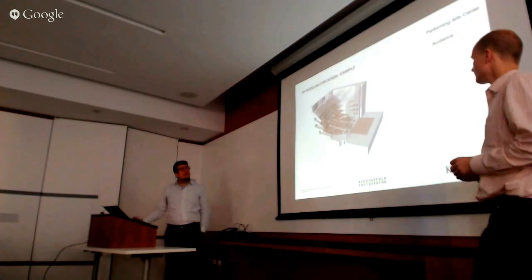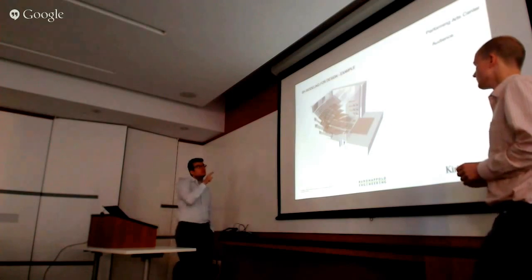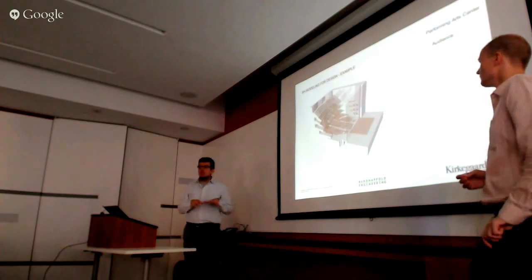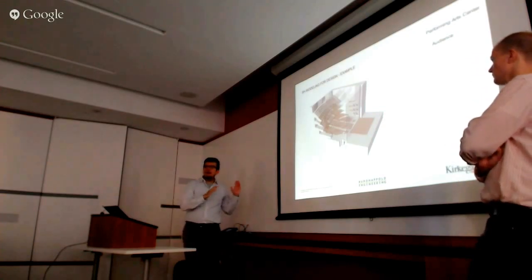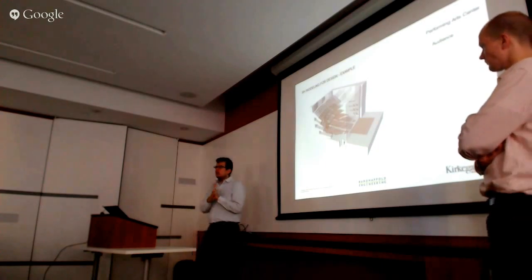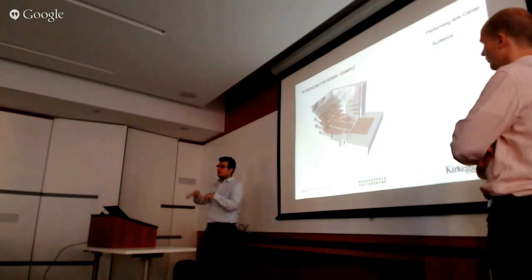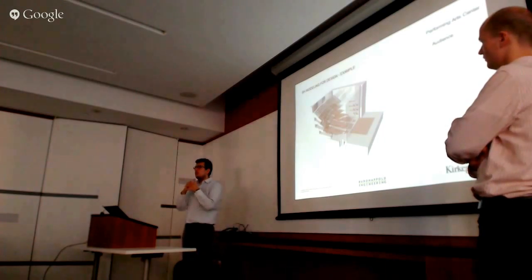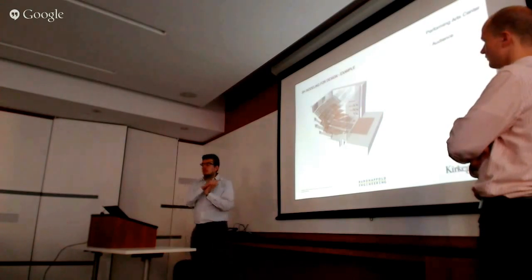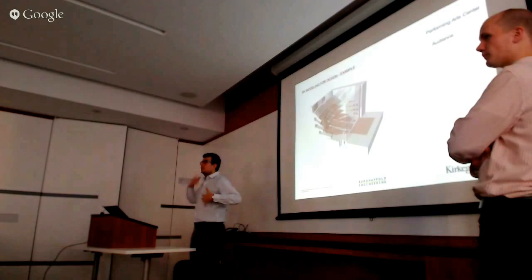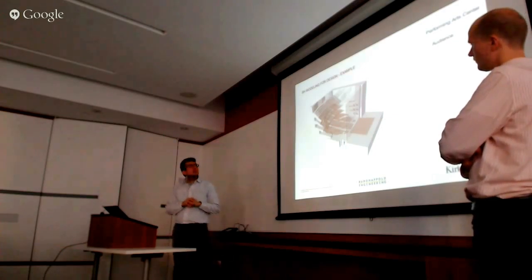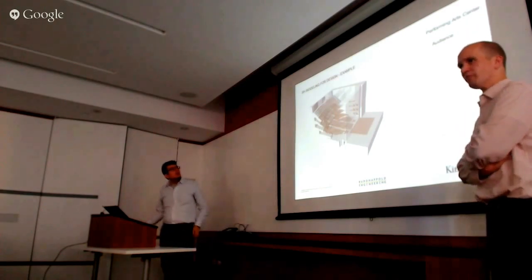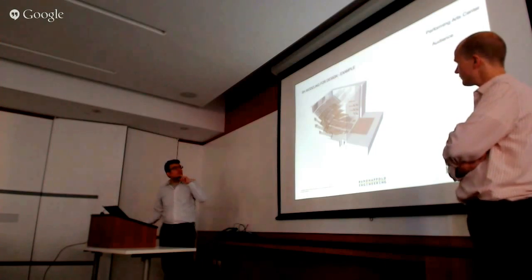And I had to build the shoebox model here because in order to model a person on a seat, I had to know how much resistance it has to the air. So I took the person sitting model at a very small scale and ran a bunch of air through it, and then adjusted a box that represents the whole thing without all the shoulders and head and legs, but it behaves exactly like a seated person in terms of restriction of air. And that was one sketch model built for this.